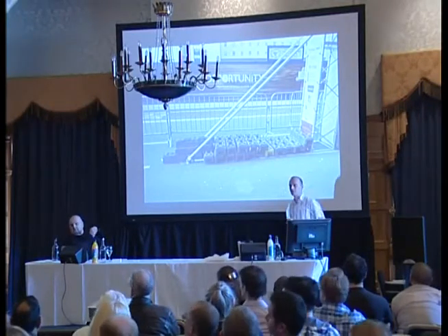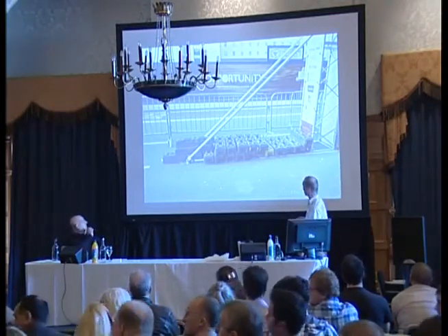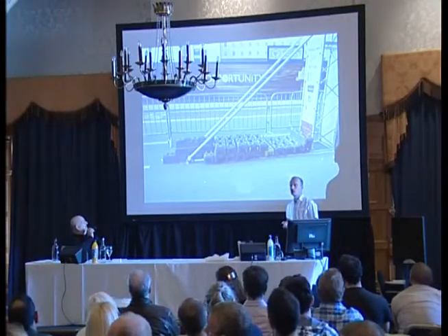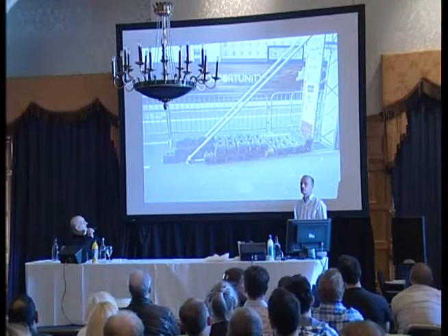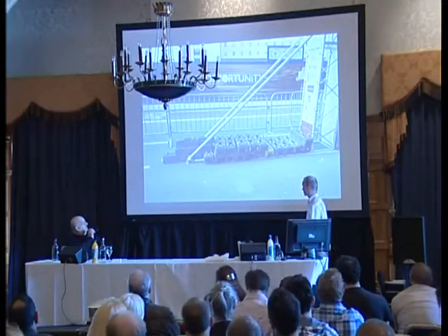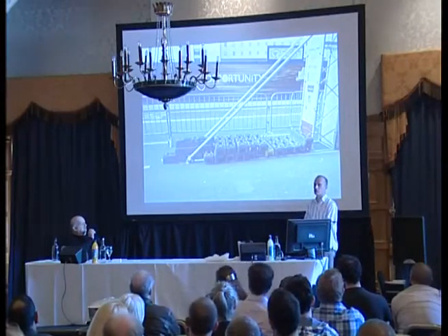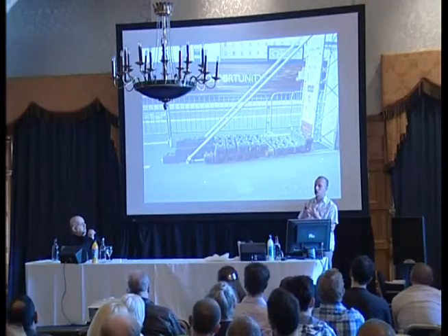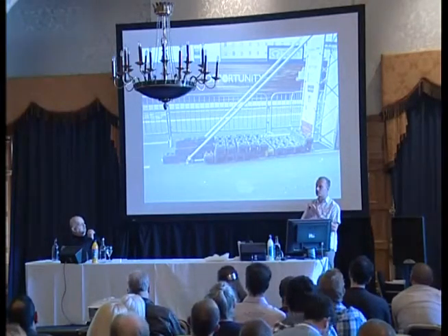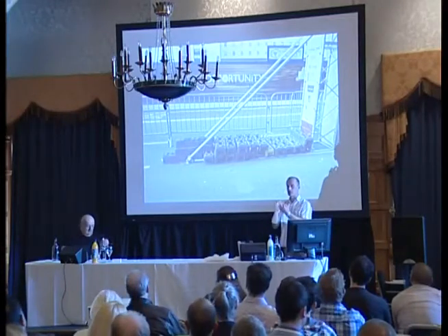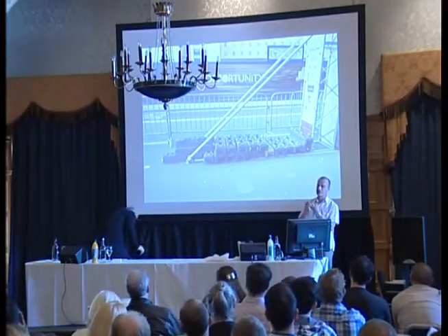Warren: Yes, just a quick one on that picture there. It shows you the weight, but it doesn't actually show you where it should be. A good engineer would show you where the weight would be, and I bet it wouldn't be spread out like that in a lump. Thank you. That's another fine point. So there's a third thing that we need added to our list of useful information that we can have from an engineer, which is where exactly that reaction, that ballast, whatever it is, needs to be.